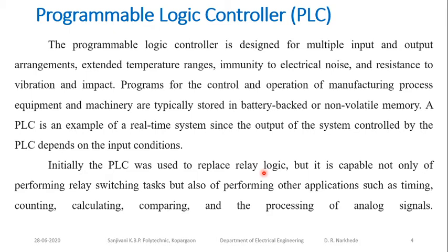So in a programmable logic controller, what we are doing is replacing the relay logic with the help of programmable logic. For that purpose we commonly use the language called ladder logic language. There are other languages also, but all over the world the most commonly used language is ladder logic. But over a period of time, the PLC does not only replace the relay logic, it performs relay switching tasks and other applications such as timing.